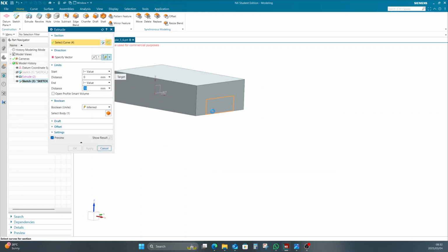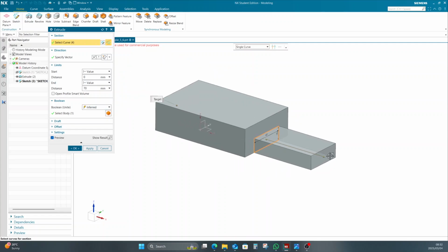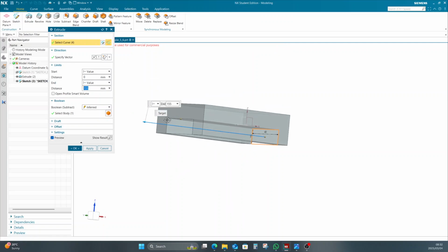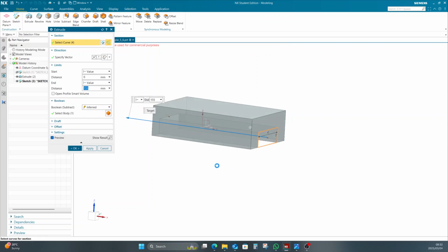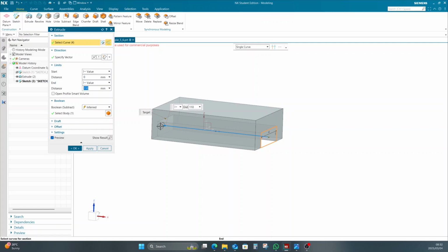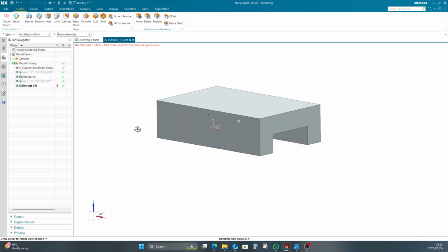Then I'm going to extrude it. This will be a subtract extrude, but I'm just going to use invert because it will detect that it needs to subtract. So it can go beyond that limit because there's nothing to extrude here anymore, and because it's a subtract, it doesn't create any features. So you don't have to type in the exact dimension there. You can if you want to, so that 110, and then the extrude is up until the end point, but you can also just drag it throughout the entire model. So that's quite easy, adding that feature using the subtract. Now that sketch, I'm not going to use that again, so just hide it.